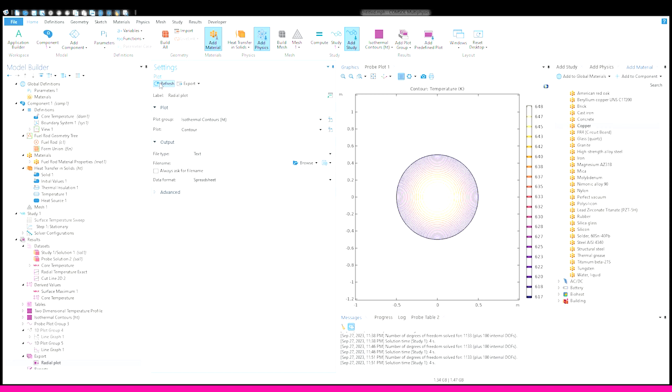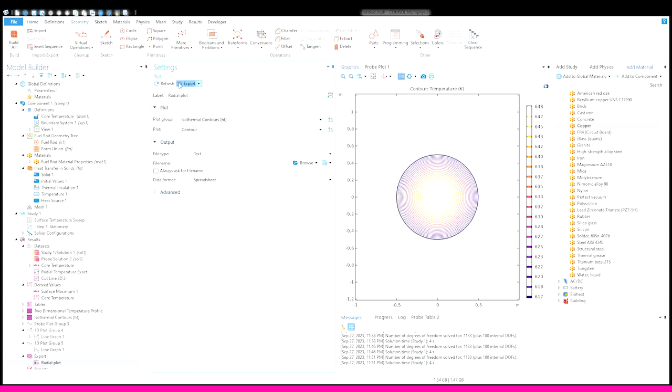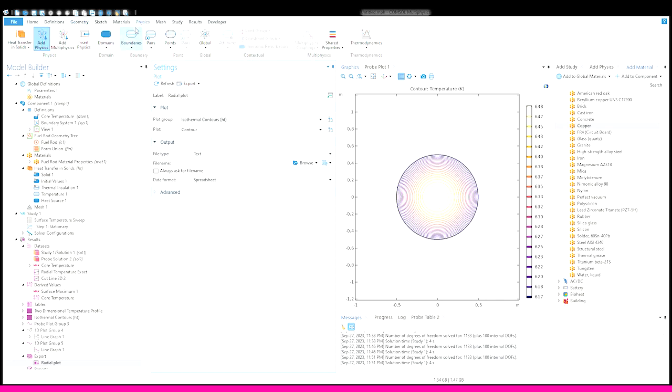I will show you in other tutorials how to make more complicated geometries, and of course expose you to more of the physics toolboxes. But really it is pretty intuitive. You determine a conservation equation for a control volume, and then you use boundary conditions to connect it to the outside world or to other control volumes, and you just compute it. And then of course you have to specify things like material properties and initial conditions, but it's pretty straightforward.